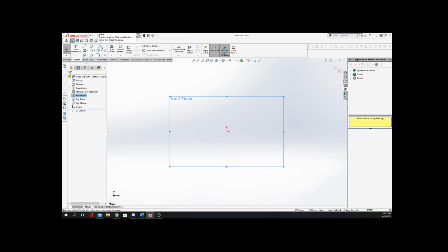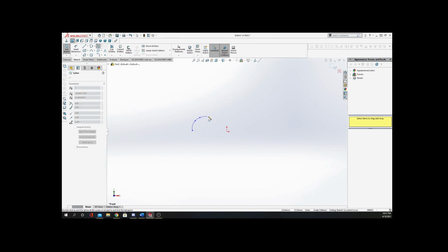Next thing we'll look at is spline. Spline is kind of a free-form line. So if we click on spline, every time you put vertices in, it lets you then turn from that line. This would be handy, say, if you were trying to follow a curve around something natural, and you wanted to bring it in and add that shape to something that you were building. Or say if you were using this to do some sort of river designing and you had to follow the river line in a map, this could help you do that.